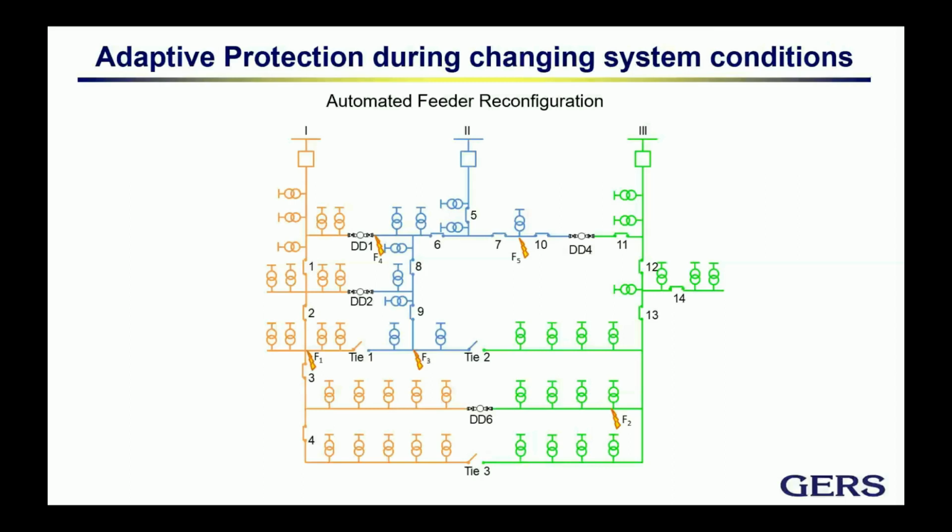Step number 3, upstream restoration. Immediately, as soon as I isolate the fault, I close the breaker and feed up to exactly section switch number 2, of course. The fault is actually here. Step number 4. So these guys between section switches 2 and 3 remain in service, but the other loads can be transferred. So in this case, you can see here that if I close tie 3, I will send all these loads or connect all these loads with the feeder number 3.